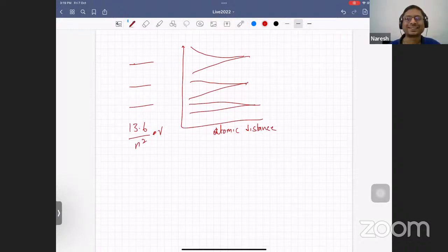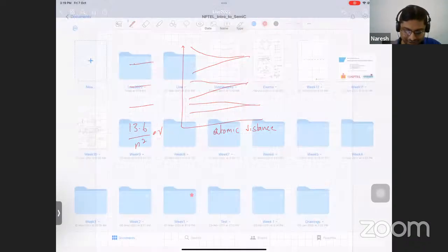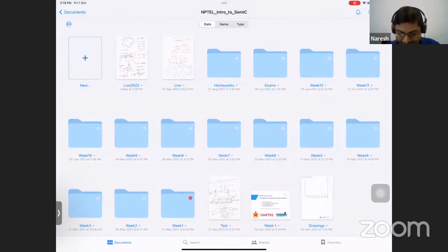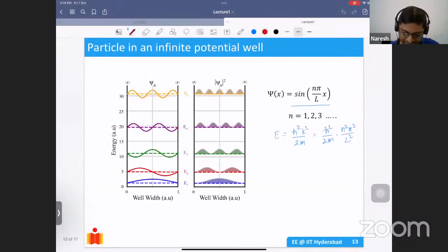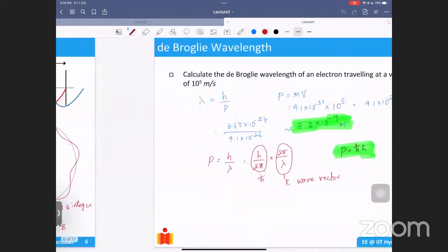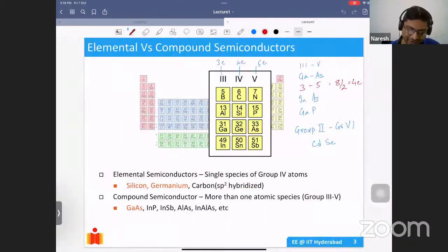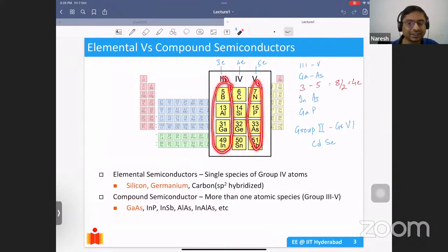Well, physically. Okay. So you can use any of the fifth group elements, right? Nishita, you look at my first week, I think I discussed it in the first week, probably even the first lecture itself. Donor elements. Exactly. If you use any of these donor elements, these have 5 electrons in the outermost shell. That's why we know that it's an N-type semiconductor. If you use P-type, these only have 3 electrons in the outermost shell, so we get P-type doping with this.